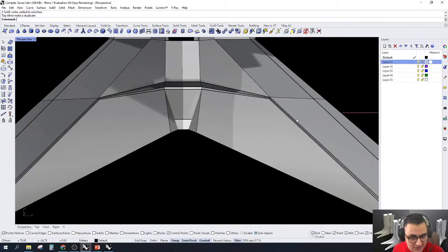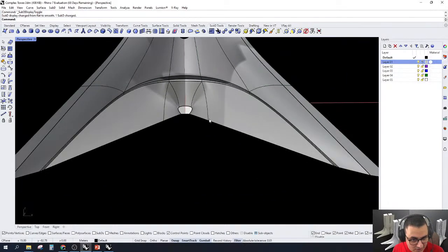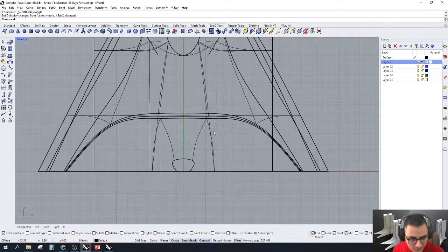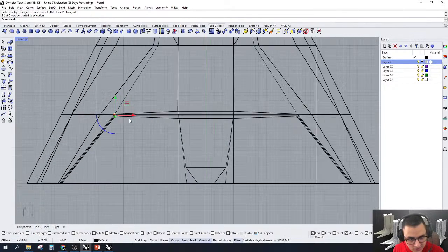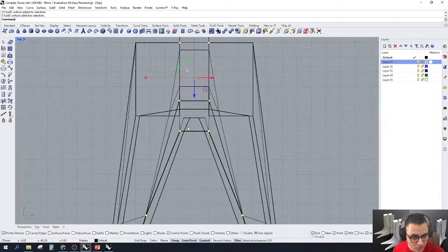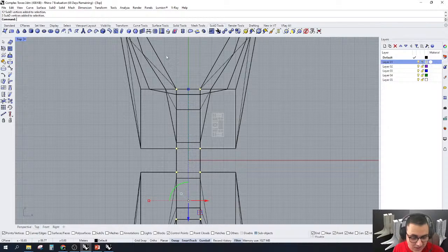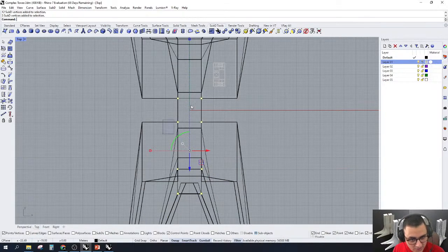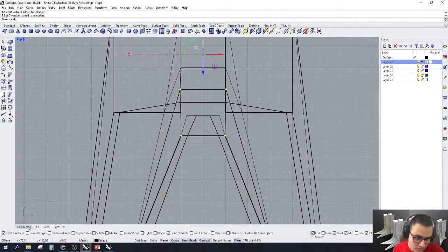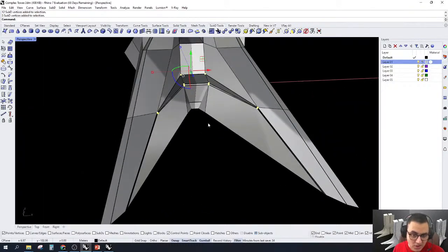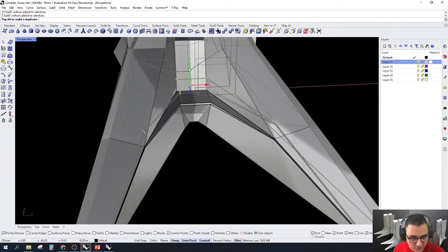Of course, in this case, the entrance is looking weird, so I need to lower this part a little bit. So I need to go to the front and simply select those, and I will go to the top, making sure that I didn't select all of the other things that I don't need, like this, and simply click Control and remove these. Maybe I don't need those two. Actually, yes, I need them. And simply drag them down there.